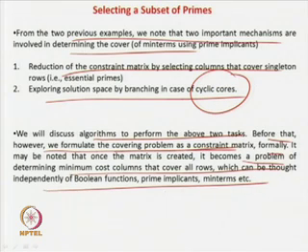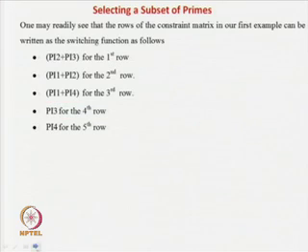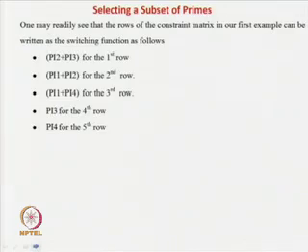So now we will see that this whole problem of prime implicant selection is independent of prime implicants, minterms, functions, etc. It can be thought of as minimum cost columns to cover all the rows. That is what we are going to do. We have a matrix, and if a column has a 1, that means that column is covering some row. Then you have to find the minimum cost, or the minimum number of columns, such that all the rows are covered. That is called the minimum cost columns that cover all the rows. This is the problem, and we can treat it independently of circuits, functions, minterms, etc.